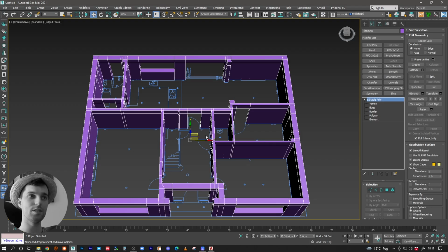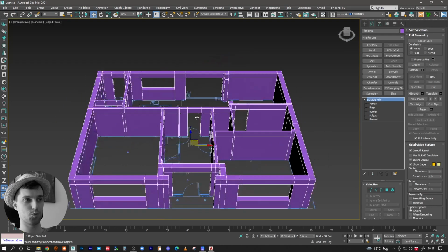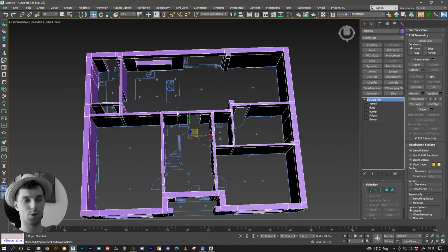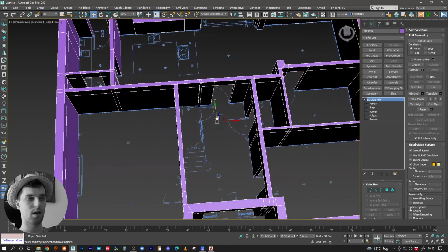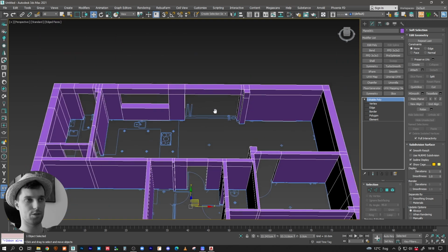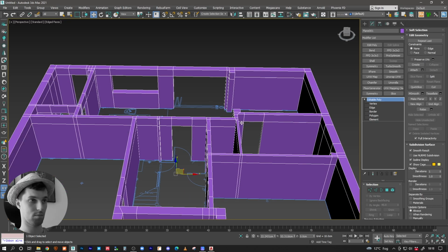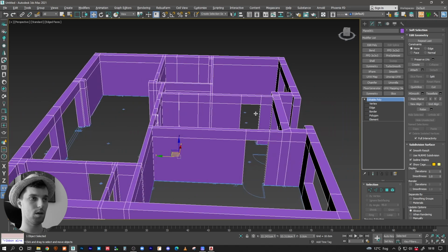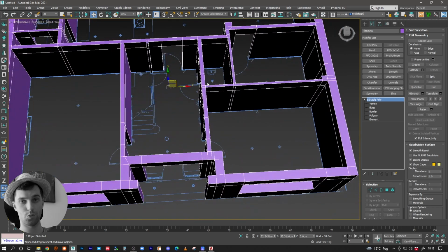But obviously there is a tool, there is an approach, there is an option for every job, right? And every job can be different, right? But for these 5 rooms, 3 rooms, 6 rooms, interiors, definitely try to practice poly modeling like this. It will become faster and faster. You just create a plane, extrude it to 210, cap it, let's go, that's it. So I think it took a while to show this, but I didn't want to speed it up.